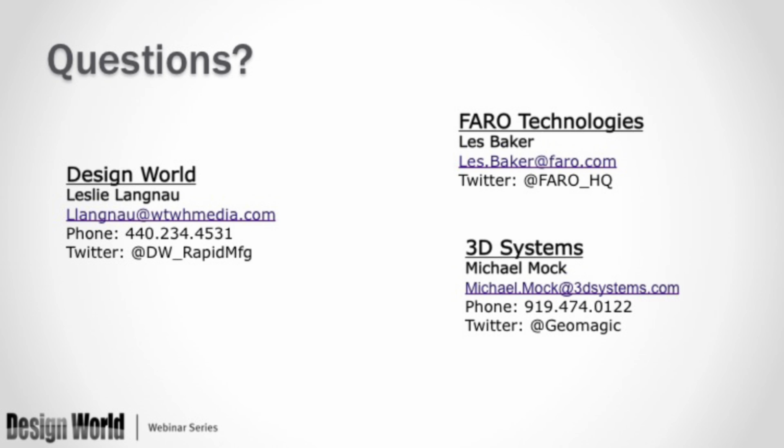Okay, this one is for Les. Can the mesh cloud be brought directly into Creo 2 or SolidWorks 12? I'm not familiar with Creo 2, and I believe that SolidWorks 12 can sometimes be a licensing or a module issue as to how much data it will actually allow you to handle. SolidWorks and the Geomagic products handle most of the industry standard formats. So I'm almost positive that there's a clean way to get the data from one software to another. But the bigger issue is probably whether SolidWorks has the horsepower to handle the amount of data you might be considering transferring.